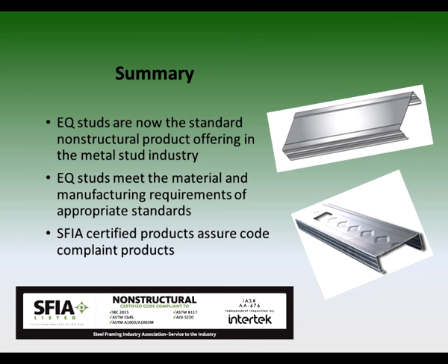There's one final set of key points that I'd like to emphasize. First, EQ studs are not really a new or unusual stud in the market anymore. They are the predominant product being used in the market for non-structural applications. Second, you don't need to worry about performance. Code-compliant EQ studs, just like conventional studs, meet the product requirements and the applicable standards that govern CFS framing. Last, if you want to be sure the standards are being met, the SFIA label is the best place to start.